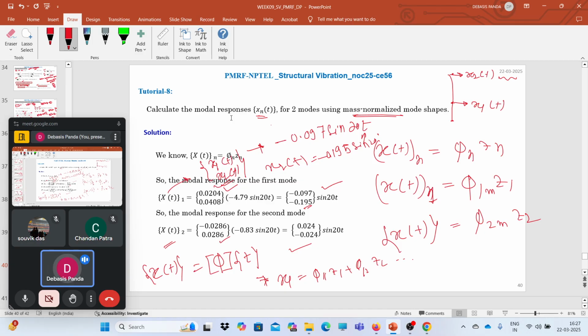You can solve that 5 degree of freedom system in modal coordinates. You have the modes information, or if you don't have it, you just solve the characteristic equation. You will find the eigenvalues and eigenvectors, which are the mode shapes, right? Then you do the normalization, and you can solve the responses. I will show you how we can do that.